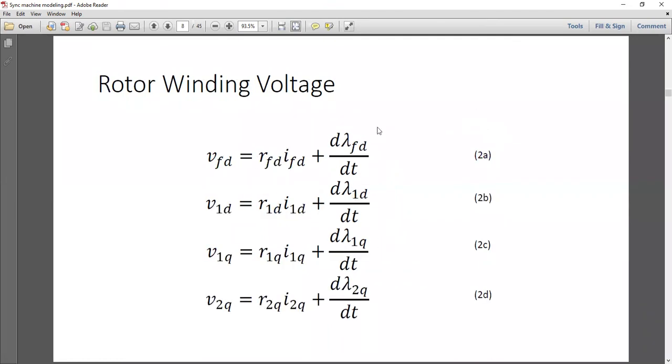Okay, so now come back to the synchronous generator, which we were discussing earlier. Any question about this? Simply because the current is being fed into the field coil, and the current will work as input to the system for 1D, 1Q, and 2Q once there are some non-zero voltages. That's why these are all plus, and these terms are associated with the flux linkage in those three circuits.